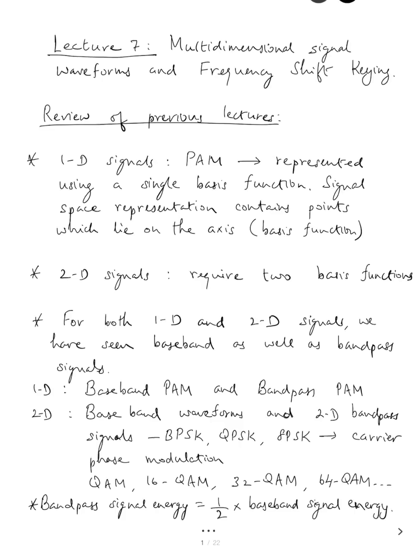Right, and another important observation we made during those analyses is that the bandpass signal energy is half the baseband signal energy. Okay, so we are going to use this concept, this idea again in the present lecture, and as we go into that, I will be referring to some of the baseband waveforms which we have seen previously for the two-dimensional case, and then extend those ideas to create baseband waveforms in multi-dimensional space.